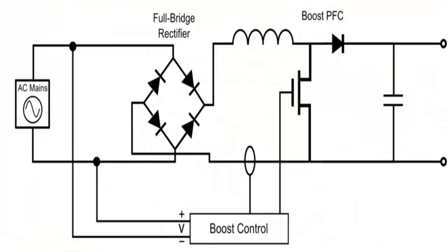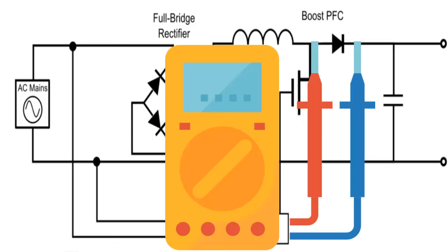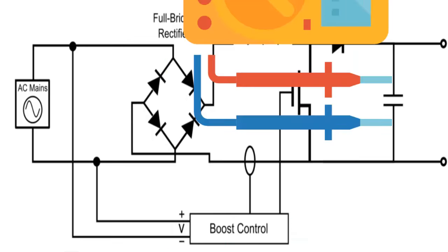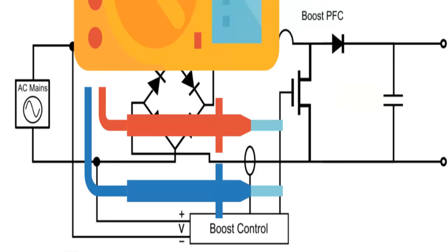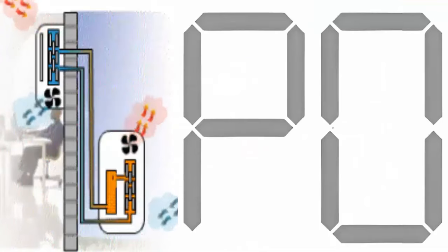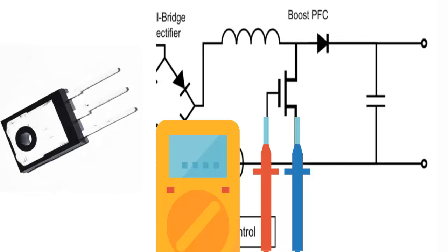8. Verify the correct values of resistors in the PFC circuit, as well as the status of the diode. Additionally, visually check with a capacitance meter the state of the capacitors, and observe electrical continuity in the card traces. 9. Check the status of the IGBT transistor in the PFC circuit.